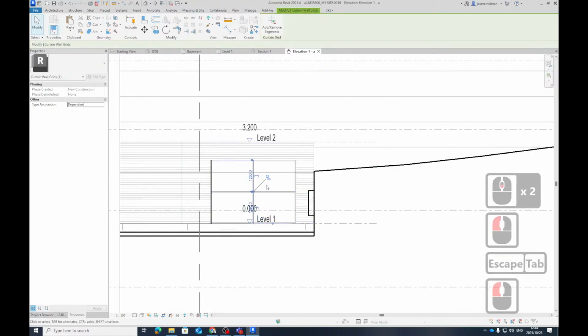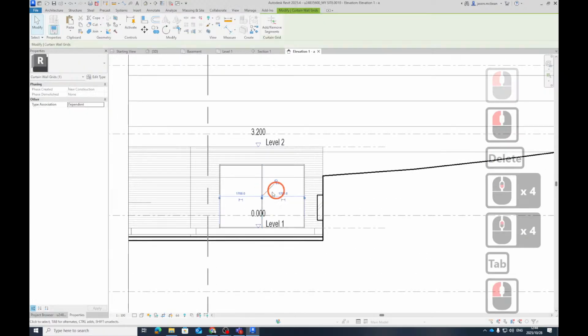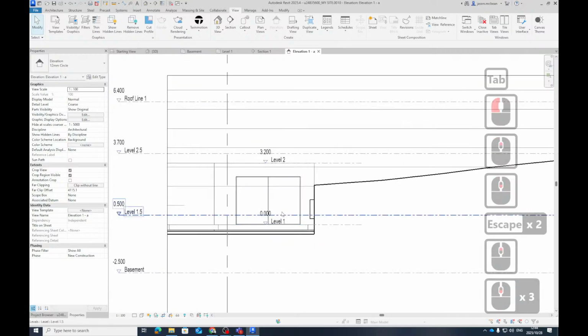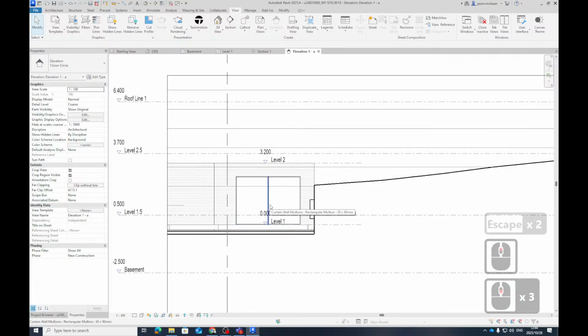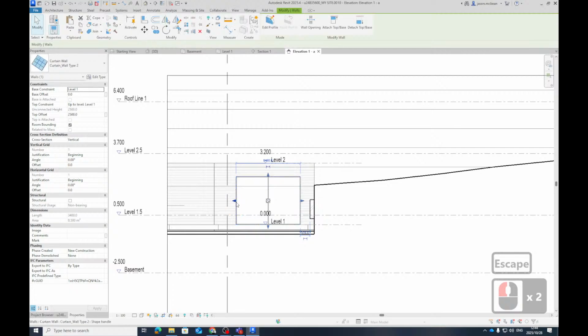This one, so now, automatically, it will add these verticals at maximum spacing. Isn't the maximum spacing 1800? Yeah, but because it will divide it into two, because of the pattern, it knows I need to divide it into two. So watch what happens. If I stretch this more, it will start dividing more and more and more.